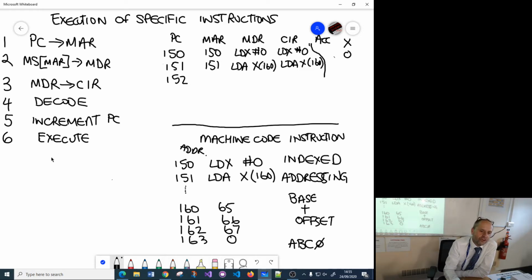We tend to draw the ALU like this, like a V. So it has 2 inputs. Right, so our 2 values are the X register, and if we look at the operand, 160. Okay, so 160 is still the data part. The addressing mode is specifying the X register. So we take those through the accumulator and we get, in this case, 160 because X was 0.